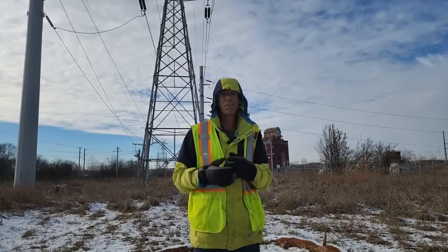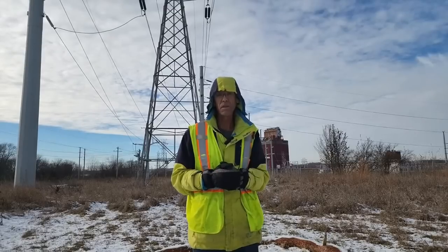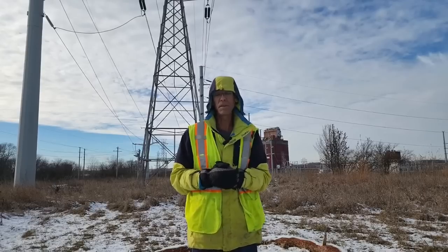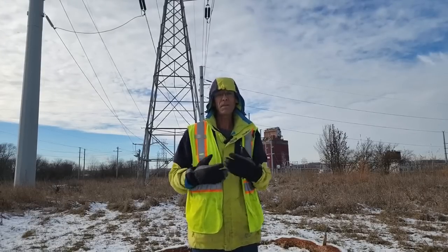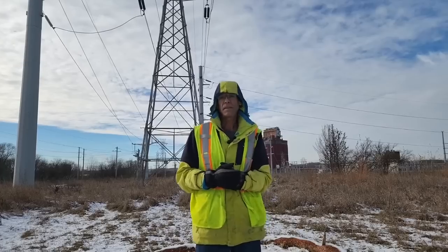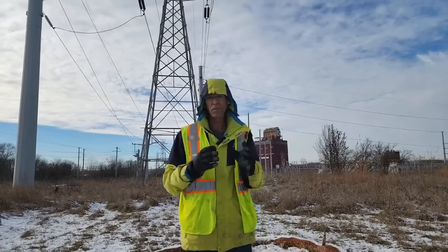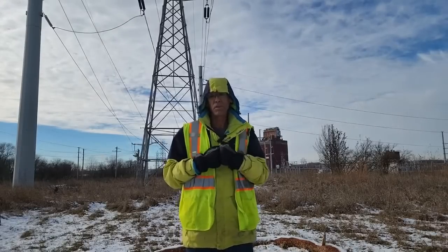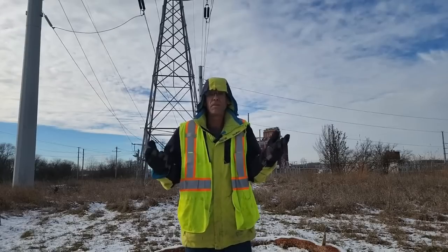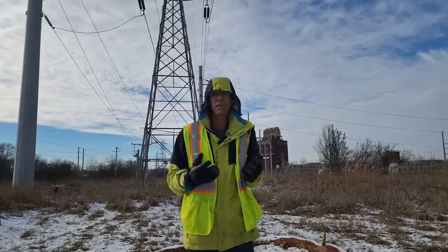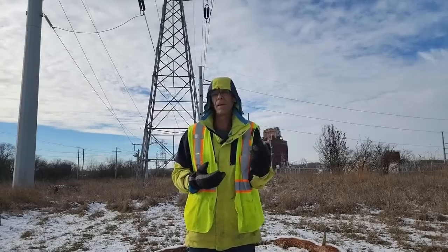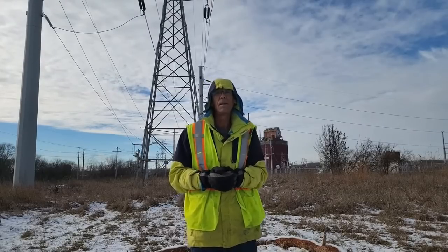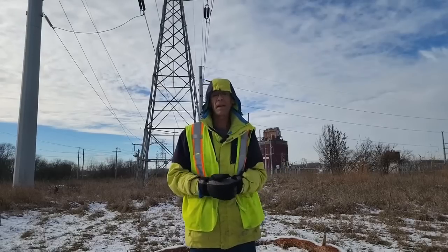So most of the time, these control points where the mitigation systems are installed, always through sound engineering practices, should have this test point, test station, test lip, control points, measurement points installed. Define them as you wish, but in themselves they consist of some measurement posts with some cables welded to the pipe, another cable welded to the coupons, and another that has a reference half cell.